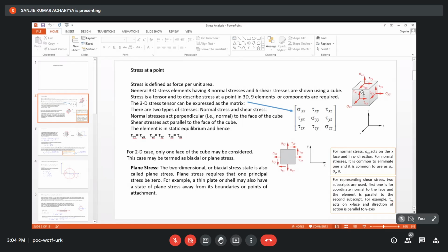So an engineer's attempt will be, if possible and if justified, to represent the stress state as a plane stress to reduce the hazards of the number of components. As an engineer, you should have an open eye within the component you are interested in analyzing. Is it plane stress? Then it is advantageous. If it is justified to assume plane stress, you will assume it. Otherwise, you will do 3D analysis. Is my point clear or not?